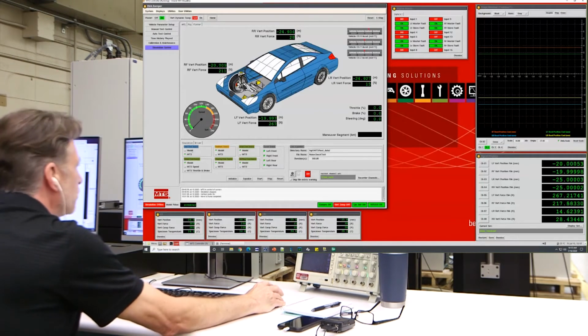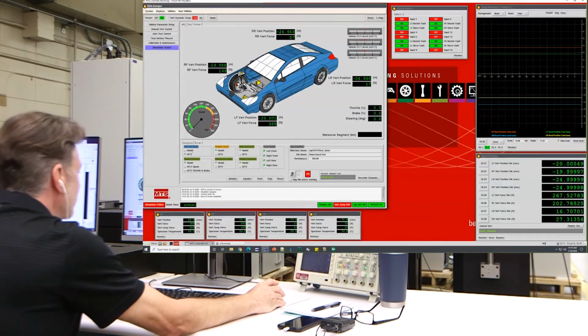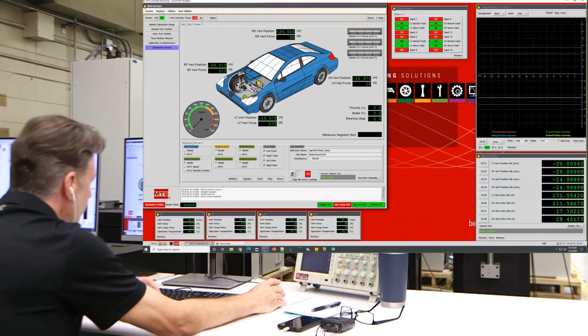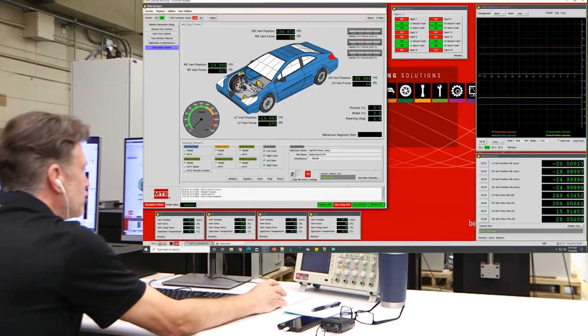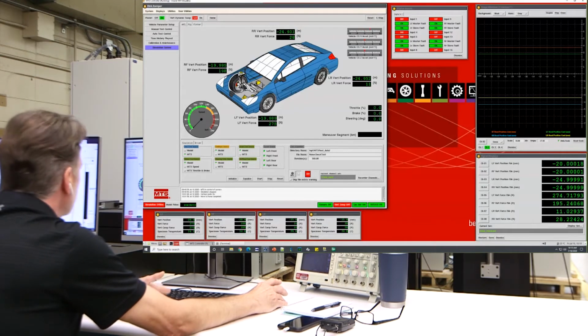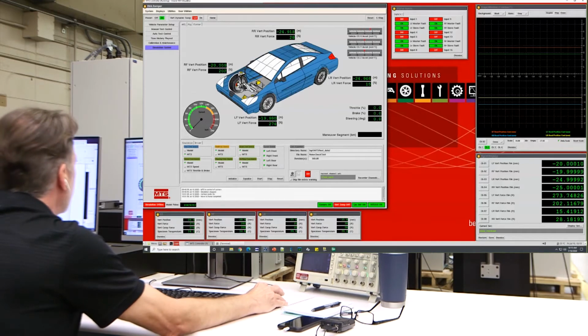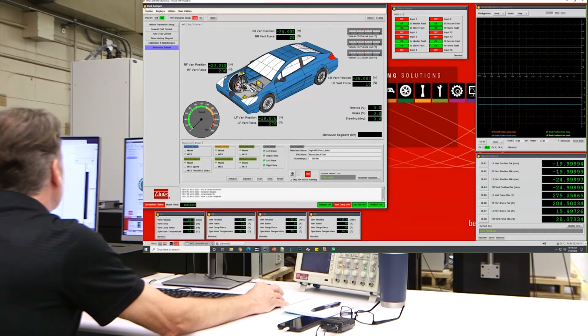This button is what's going to change our internal command switch from the function generator or just our internal set point to the vehicle model coming over that high-speed link. This button in turn also switches the feedback source from the model to the damper frame. So we're going to be taking the physical force measured from the damper frame based on the velocity input to the damper. We have a few more controls that we can take, which are, for example, the road.